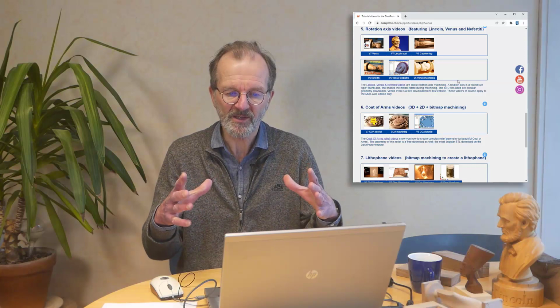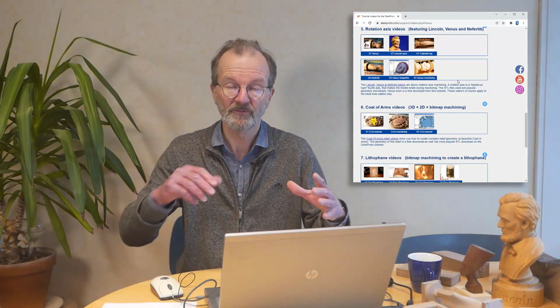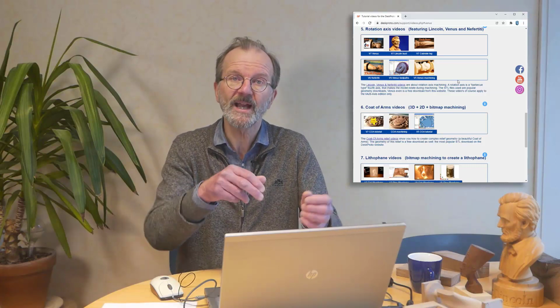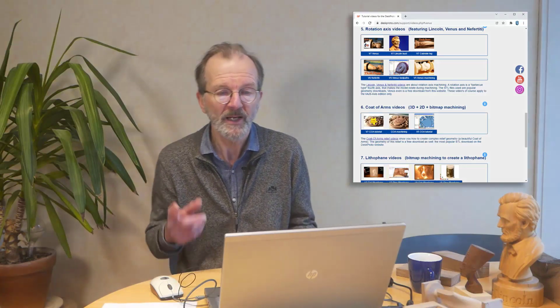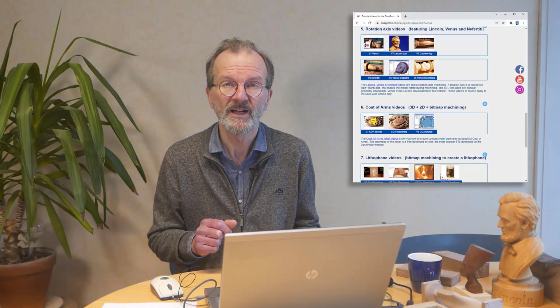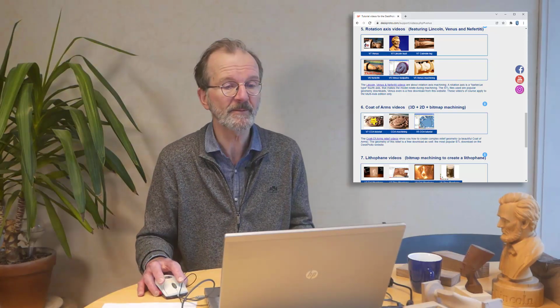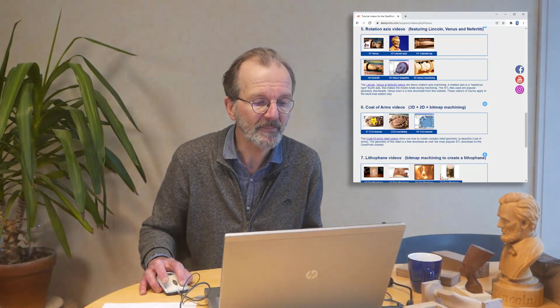So use a simple 3-axis toolpath from one side, then rotate the part, again 3-axis toolpath, etc. We've made two simple animations to show you the difference. Here they are. Let me start one. This is about rotary machining, a very simple object like that you can see when viewed along the rotation axis. You see this box. This is the toolpath.